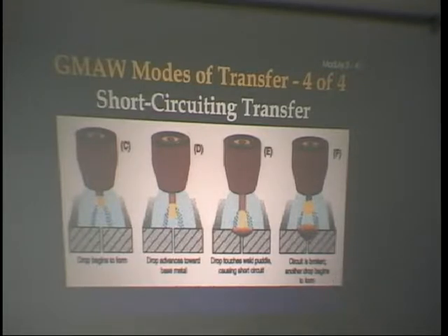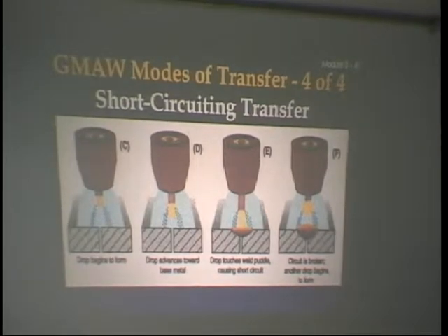The thing about short-circuit transfer is that, and please remember this, write it down someplace on the side of your book, it has the lowest amount of heat input of any of the gas metal arc welding processes. It is also one of the lowest heat input processes of any of the welding processes out there. So that's very important to remember about short-circuit transfer. If you don't know the proper techniques, your welds can fail due to lack of fusion. Okay, so study figure 21-15 in your textbook.